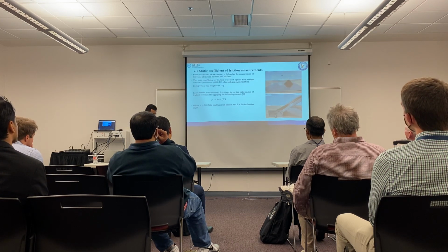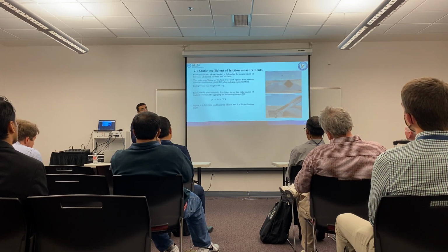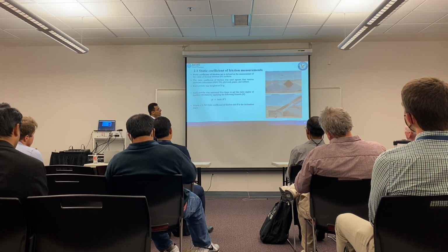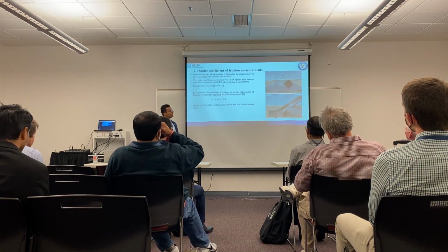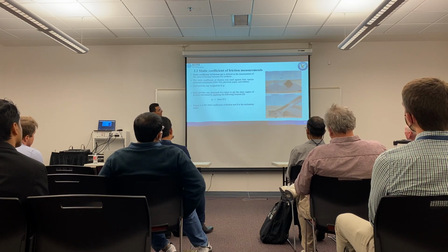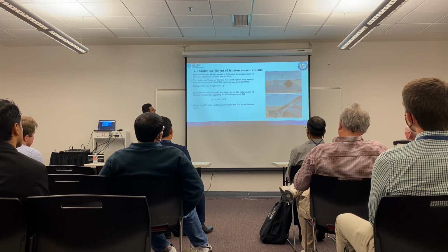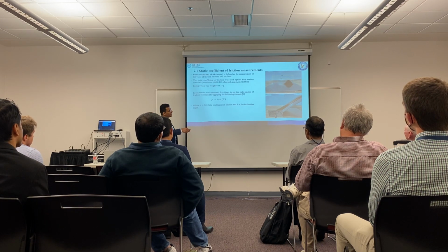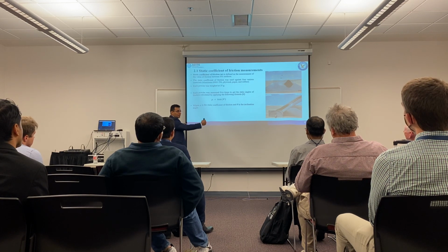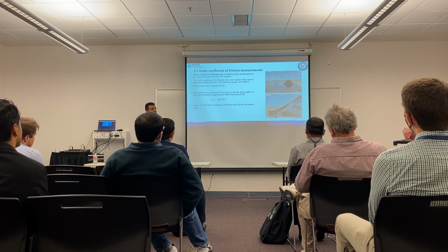The other physical property is static coefficient of friction measurement. We used 4 different surfaces: aluminium, plywood, paper, and rubber. We put the heap on the surface. We have 2 ends, a free end and a fixed end. We slightly and continuously raise it little by little, until the whole powder heap is pulled down at the fixed point.